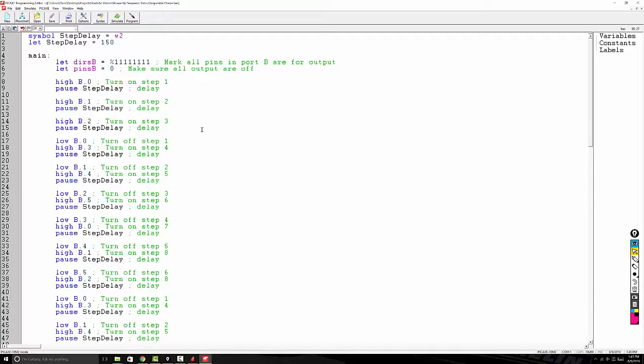Once you've written your program, now it's time to just simply upload it to your PICAXE. So remember, the two requirements are that obviously your serial connection is made through USB to your computer, and your PICAXE at this point should have 5 volts power. So in our project, the 5 volts power is supplied through the adjustable voltage regulator and then through the 5 volt voltage regulator. So if everything's on, which right now mine actually isn't connected, so I'm going to get an error here. But if you've done it right, you will not get an error.